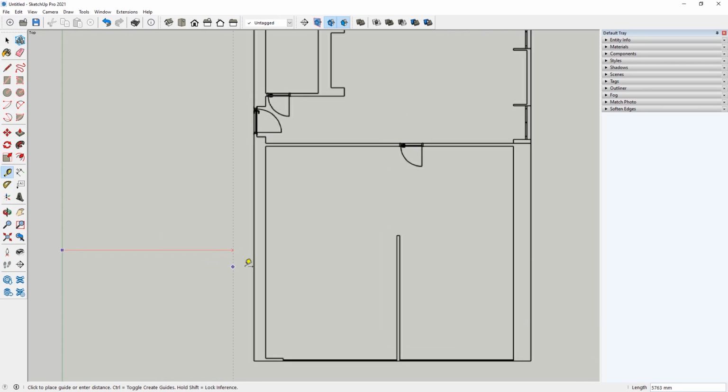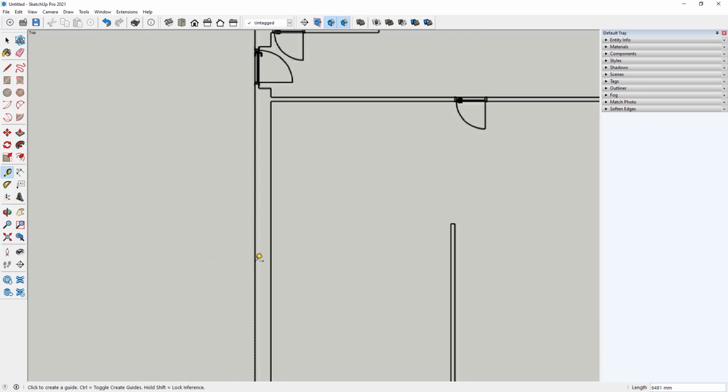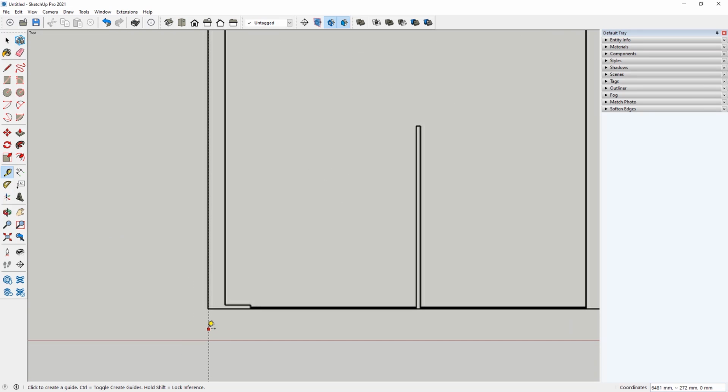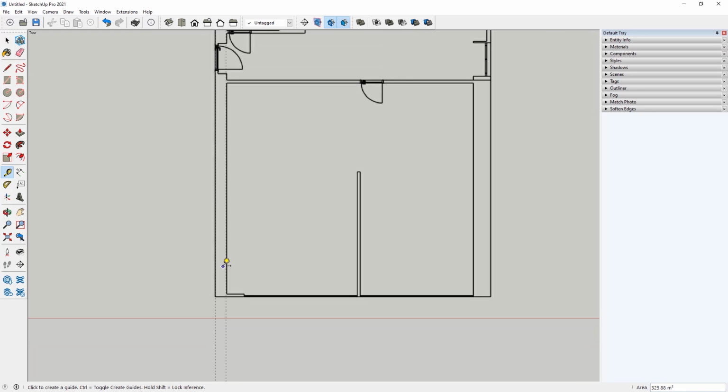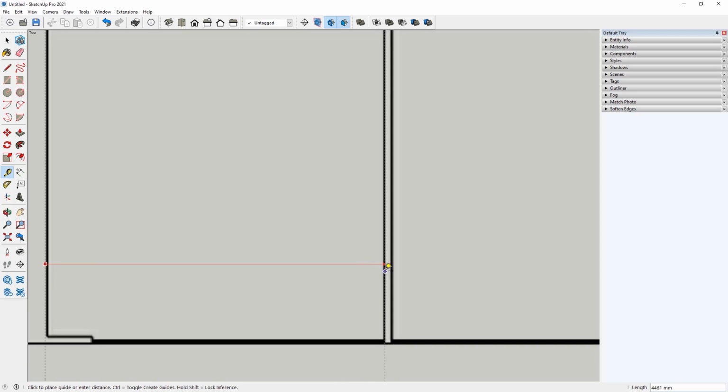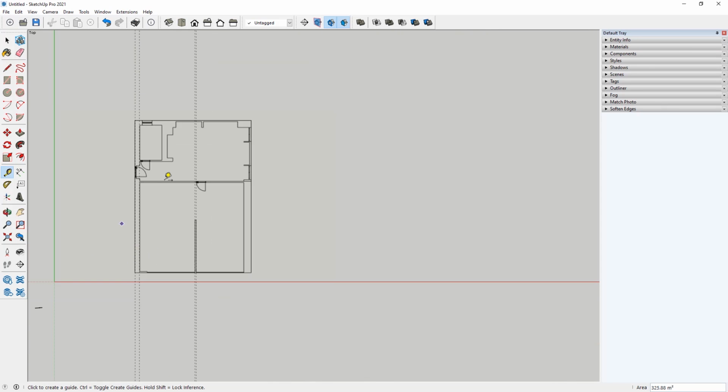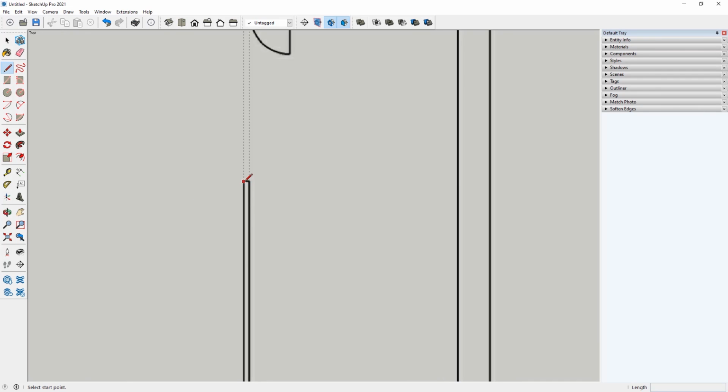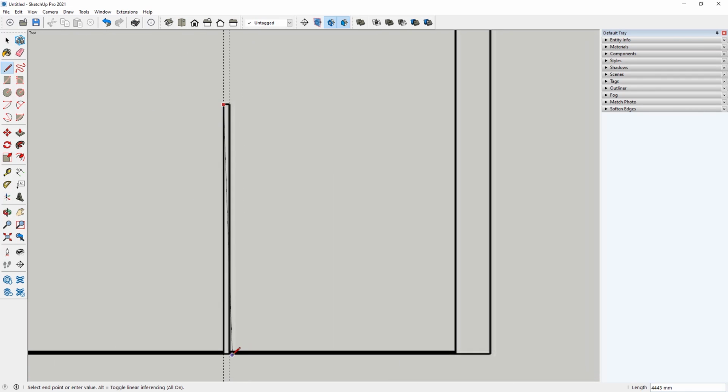The reference lines come from the horizontal and vertical axes, and we just offset each reference line by some dimension to cover all the walls, as you can see how I made it right now. And after that I can use these reference lines to build all the necessary dimensions to create our walls.